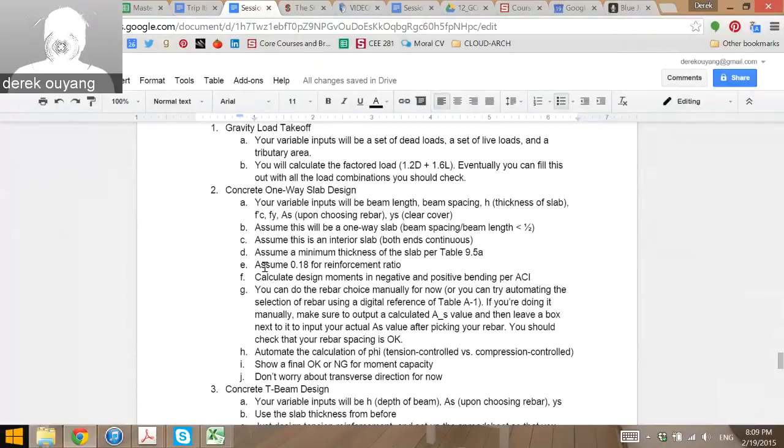So that's, you design, you figure out your B, which you'll be designing for. And then you're still pretty much just designing it like a rectangular beam. Of course, you want to check 2 possible conditions, right? Either the A is within the flange or it's not. I'm going to guess it's almost always going to be within in this case because you've been super conservative with most things. But feel free to just assume that it's within the flange for assignment 6 or build in the check for yourself. Like you first check if A is less than this, then do this. If it's greater than TF, then do obviously a harder geometry calculation for the Whitney stress block. Just if you want, you could just assume it's almost always going to be up there, right?